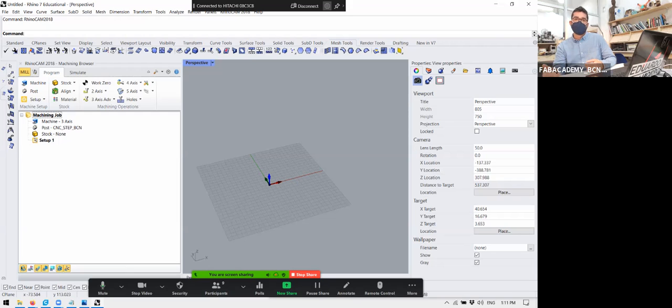I have assembled a few CNCs, and some of them were running the first generation of the firmware, and we didn't want to update to the newer one just in case. Actually, we did update, and the machine stopped working properly. Like 1 out of 10 cuts was doing weird things. So we rolled back to the first generation of the firmware to make it work stable.